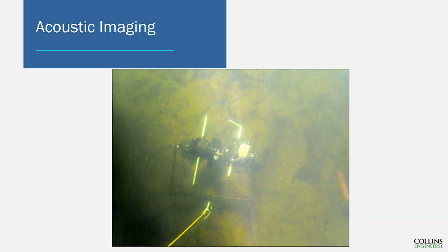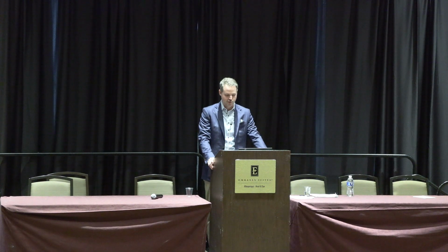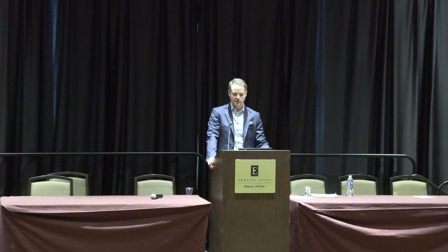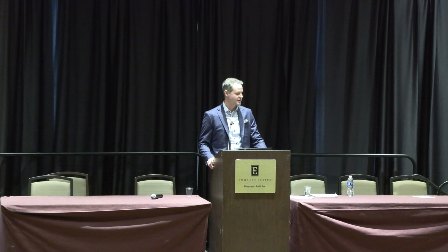So on to the final configuration. I wish I had a slightly better picture of this, but this one was taken looking down from our boat through about 10 feet of water at the sonar at Lenore Bridge. So it's basically sitting on a metal platform that keeps it just above the surface of the channel bottom. This is good for high current situations because it's much less likely to be pushed over, and it's low enough to see undermining and defects at the base of the piers, which is what we were most concerned with. We only had to put some pieces on it to stabilize it and a little bit of weight to just keep it in place. It worked out pretty well.